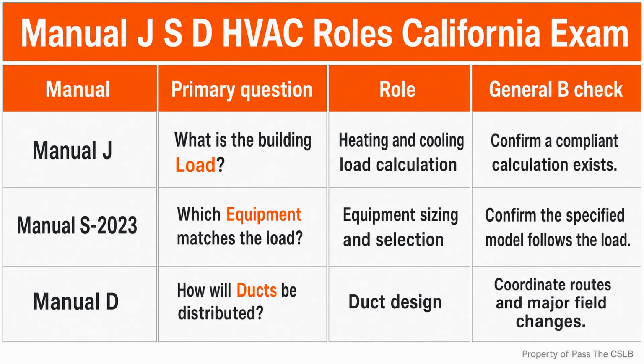The short run is the problem. The system may stop before it has operated long enough to remove moisture effectively. The space can feel cool but damp. Depending on surrounding conditions, repeated short cycling can also contribute to condensation concerns, comfort complaints, and unnecessary mechanical wear from frequent starts and stops.